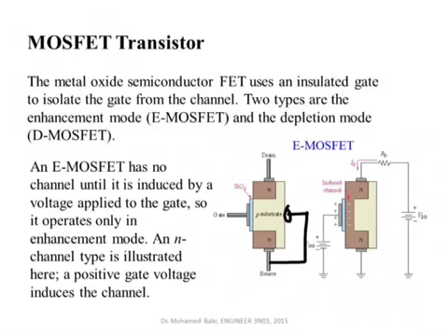So this is really the basic concept behind the MOSFET transistor. We have a capacitor. When you apply a positive voltage to that capacitor, it attracts electrons from the P substrate. All available electrons will get attracted. It will create an inversion channel or a conduction channel of electrons, and these electrons get swept away by the applied external electric field to cause current to flow. And you can control this current by changing the voltage applied to the gate. This is really a fundamental concept of the MOSFET transistor.